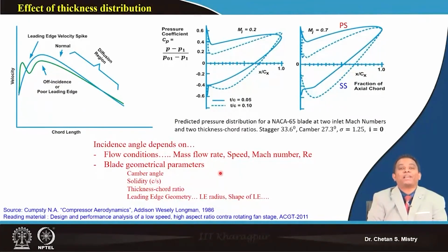Now onwards, the angles we define will be based on the blade metal angle or blade manufacturing angle. The blades we are looking at are designed and fabricated by considering the change of incidence angle. Suppose my air angle beta 1 and beta 2, mainly beta 1, is known to me; I will incorporate my incidence angle there, and based on that I will make my blades.